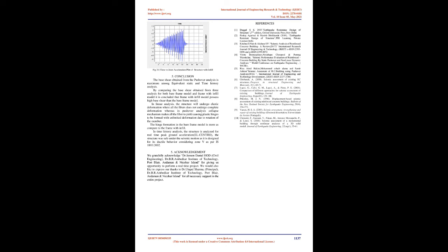5. Conclusion. The base shear obtained from the pushover analysis is maximum among equivalent static and time history analysis. By comparing the base shear obtained from 3 analyses for both bare frame model and frame with infill model, it is concluded that the frame with infill model possesses higher base shear than the bare frame model. In linear analysis, the structure will undergo elastic deformation where all the fibers do not undergo complete deformation, whereas in pushover analysis the collapse mechanism makes all the fibers yield, causing plastic hinges to be formed with unlimited deformation due to rotation of the member. The hinge formation in the bare frame model is more as compared to the frame with infill.